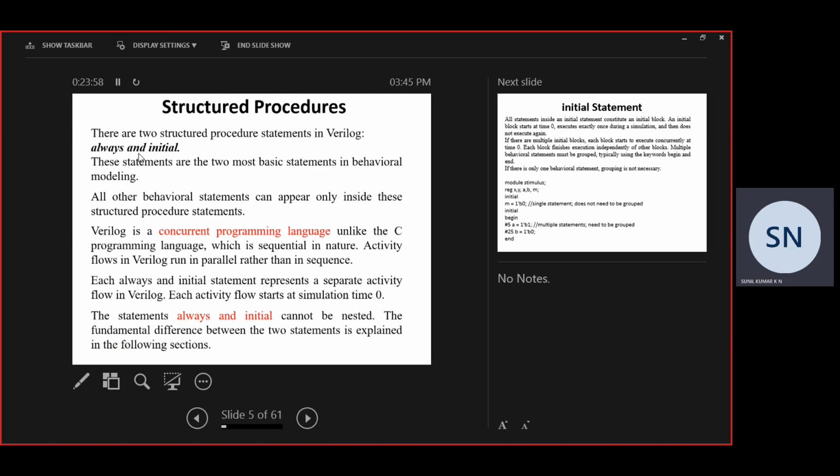So for loop, that is always an initial statement. So always and initial, if it is being used in any program, then it is a behavior level model. Always means any changes happening within the statement are being monitored, and it will be an infinite loop, that is going to work until you terminate the simulation, that is by using $finish. So it will keep on monitoring.